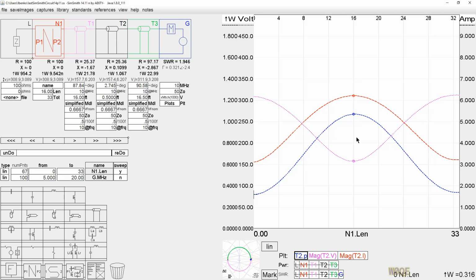Well, it's not 4 different because there's another loss in coax, and that's called dielectric loss, and this model obviously has dielectric loss in it also. We could change this model out to be a model that had no dielectric loss, and we would see a 4x difference in power. But that doesn't really change the value of this discussion. So if we look at this now for a moment and watch what goes on here, let me change this impedance to be a 3-to-1 SWR.